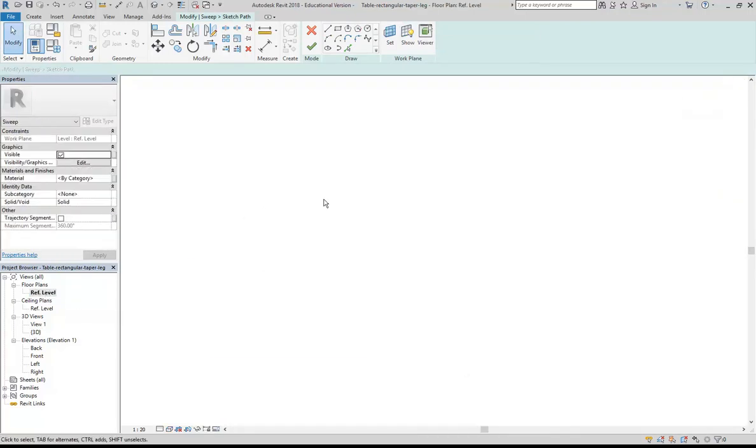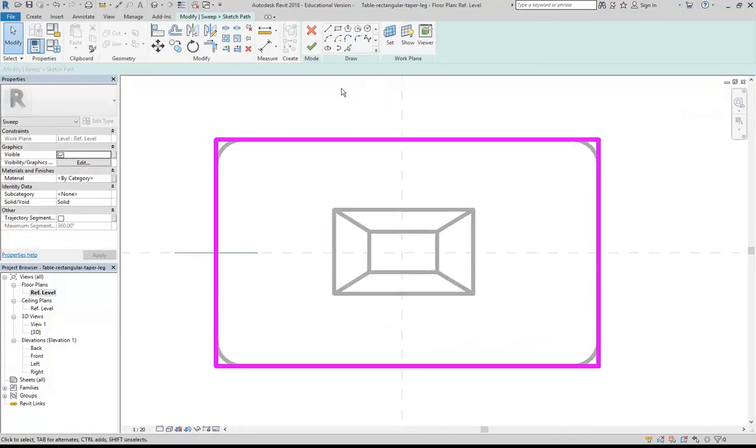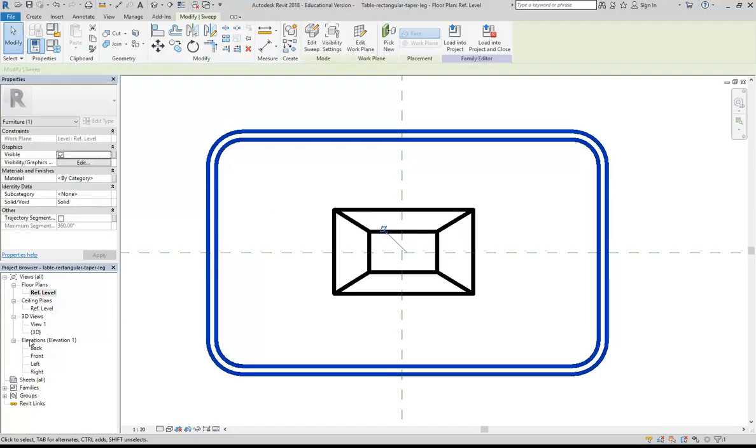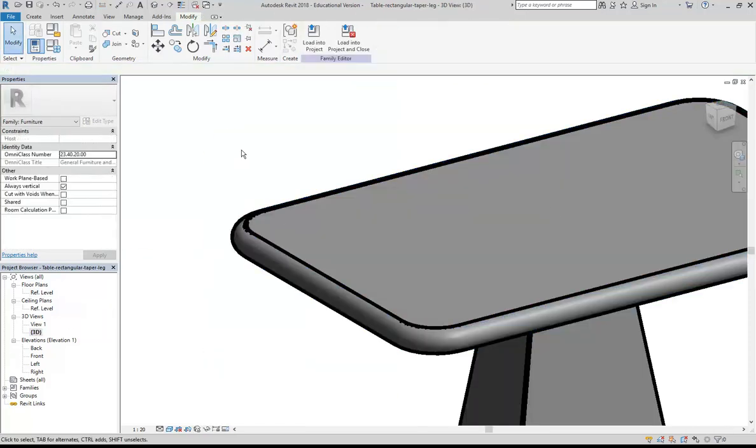And then I can go to my Plan View, and instead of drawing those fillets in again here, pick lines. Should let me pick those curves more quickly, and then just using trim, we can just join all those together. Okay, so that's my new path. If I finish that and then finish it again, of course now the sweep follows that.